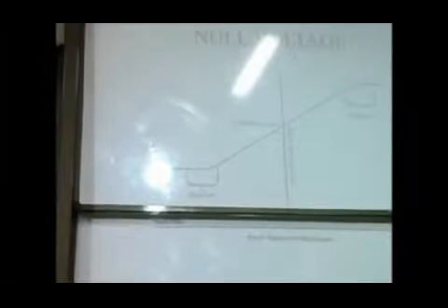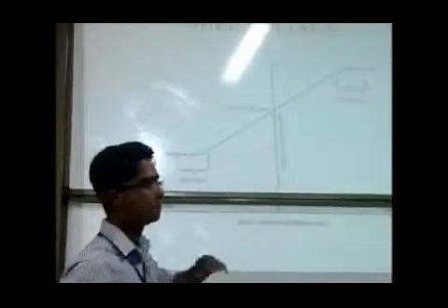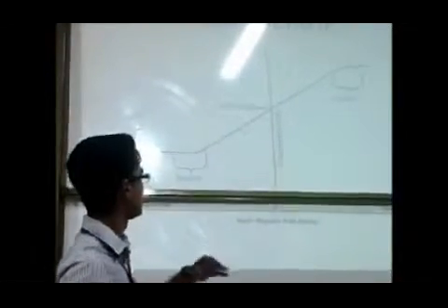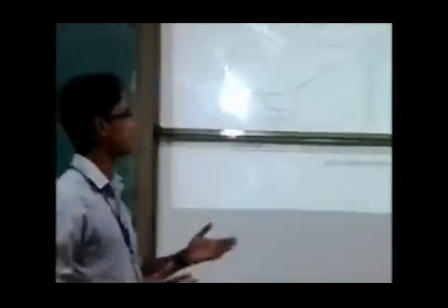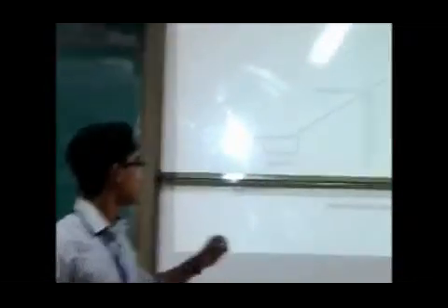And there can be some other problem, like the magnetic field can vary from positive to negative. So the output of the amplifier will obviously be positive or negative. In that situation, we would want to use two power supplies for taking positive and negative voltage.